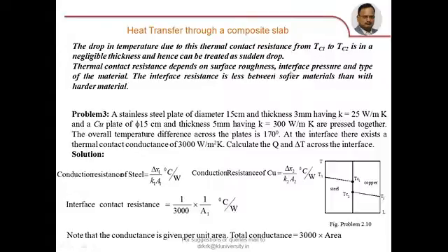Similarly, to avoid this thermal contact resistance, if you attach one to the other by applying large amount of pressure, then interlocking of the projections will take place, and thereby avoiding voids between the two surfaces, or it will expel the gases in the space, thereby thermal contact resistance decreases.